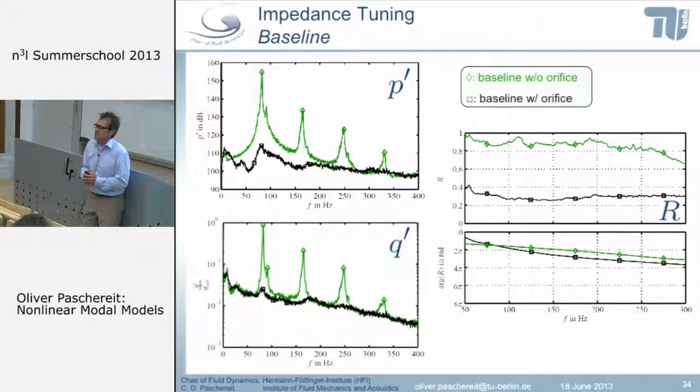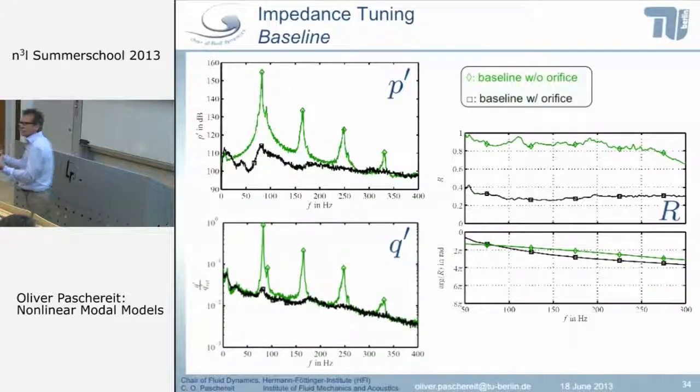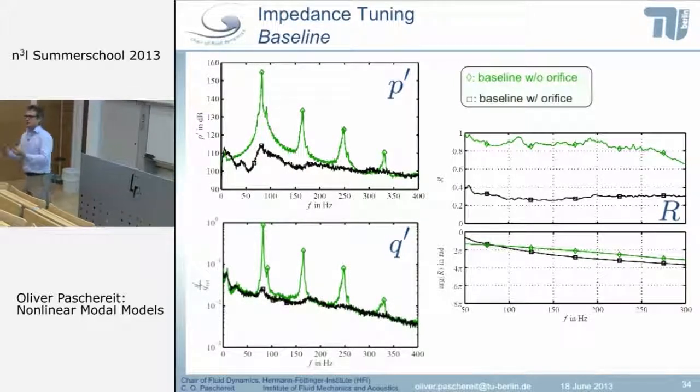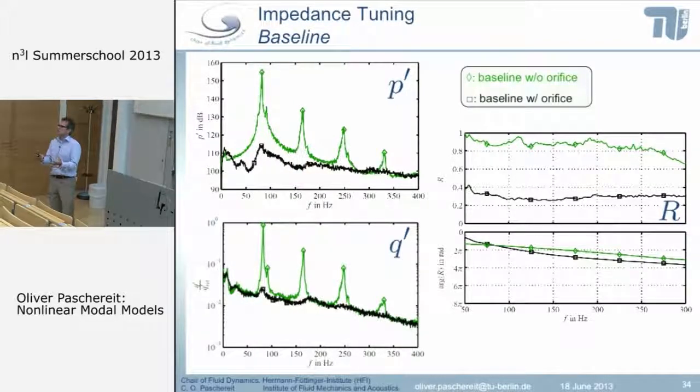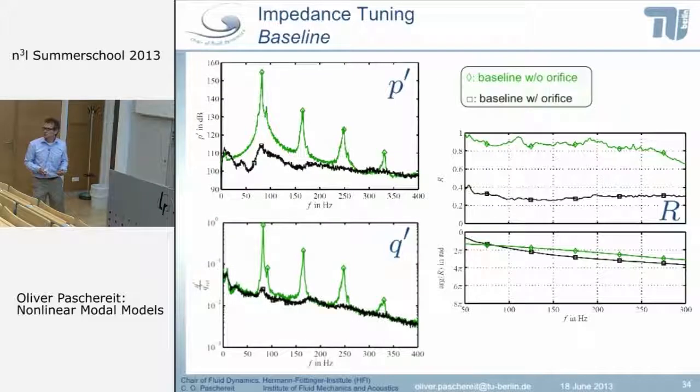There have been a number of publications by us and by others where you can see that an acoustic wave running into an orifice with a through flow creates vorticity, and this vorticity finally dissipates, and that damps your acoustic wave. So you have no reflection. You can almost avoid the reflection. The reflection coefficient is shown here, the reflection coefficient over the frequency of your orifice. So it is in the order of 20% reflection, a very small feedback only to your combustor, and a very simple method. This is the open-end reflection.